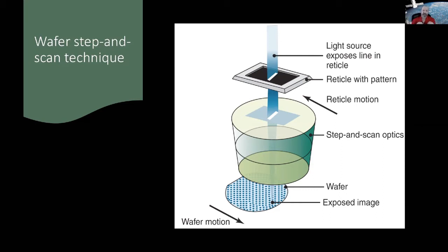And they did innovative things like have 2 granite stages. On one stage, they would pre-align the wafer while the other one's stepping. Then they'd switch the 2 stages and continue stepping, so there was very little pause between wafers. They could crank these things out very quickly. They also went to chemically amplified resists, which were faster, because it takes a certain amount of time to expose photoresist. But if you create faster photoresist, then you need less light, which means each step takes less time. So there's a lot involved in these things.